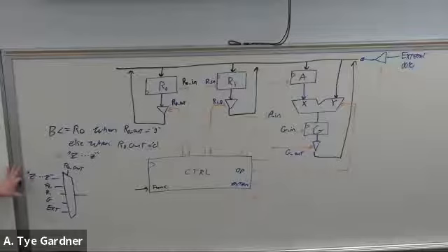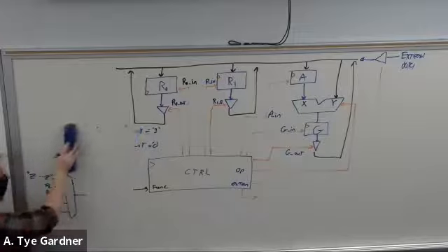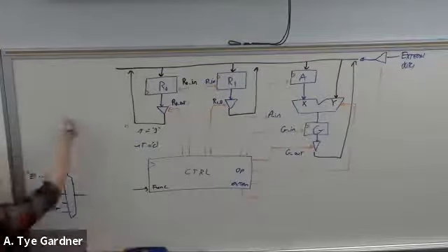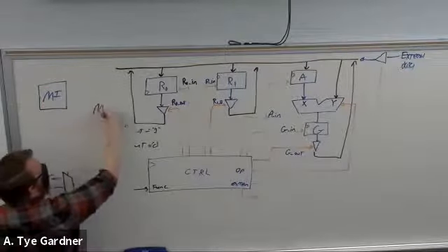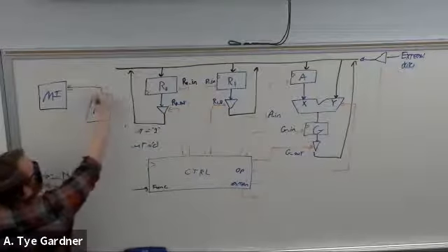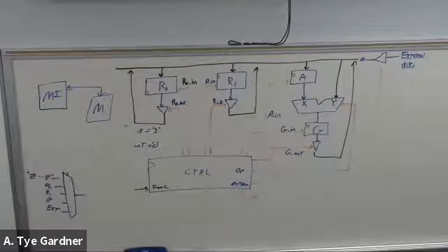So anyways, that's the kind of idea that you want to do when you're driving the bus with the memory interface. Because in our case, we have the memory interface, and over here we have a memory, and they're connected together through in-out ports, meaning that I may need to write to memory, or maybe I'll read from that memory. So we make this memory interface that has this mux.